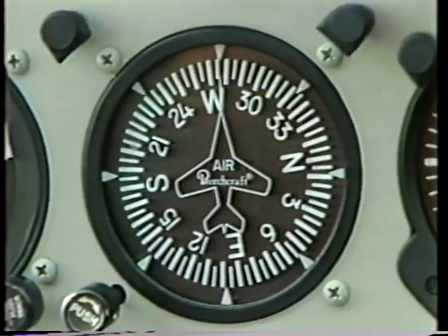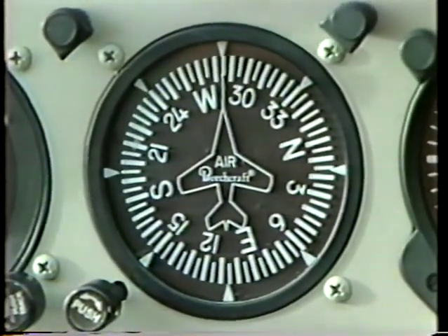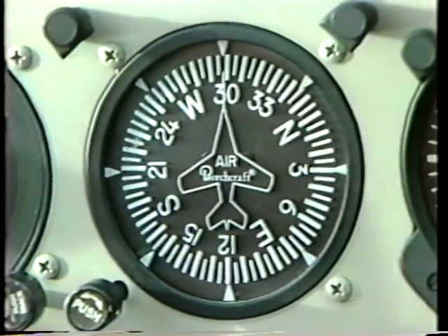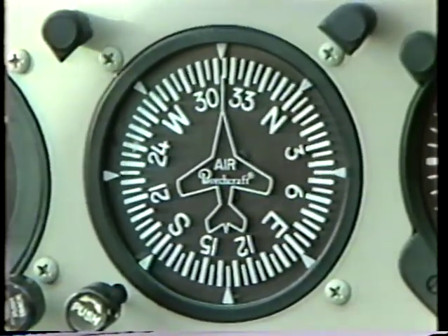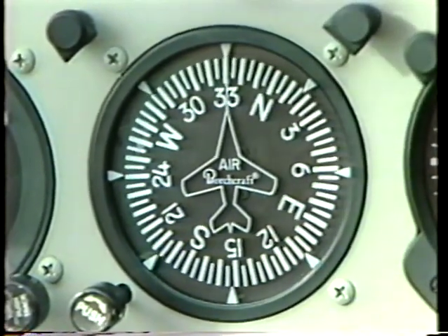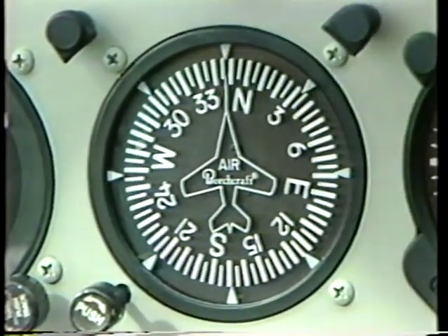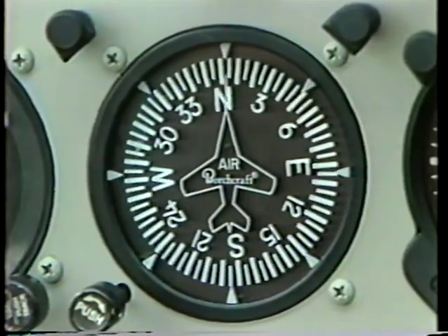The heading indicator, like the attitude indicator, is usually an air-powered gyro that uses the principle of rigidity in space to maintain stability. As the instrument case and the airplane revolve around the vertical axis, the card provides clear and accurate heading information. Except for situations involving excessive angles of bank or improper setting, this instrument is extremely reliable. Precession does act on this instrument, but unlike the attitude indicator, the heading indicator does not have the internal capability to correct for precession errors.